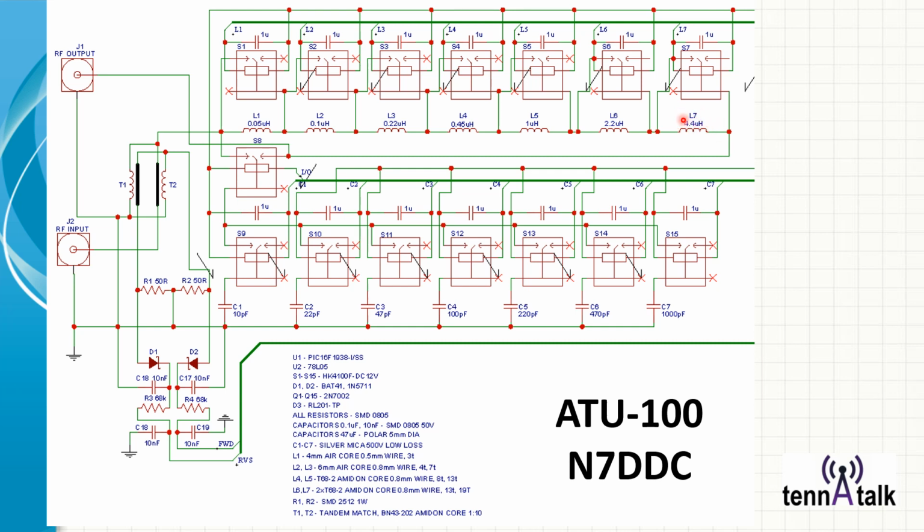Well, guess what? These are relays, and they're used to short out selectively the inductors we don't want in the path. So what'll happen is if we've got, let's say, the first 2 shorted out, the current goes through the relay instead of through the inductor. And then this one, the relay is open, it's not shorted. So we're adding 0.22 microhenries. And so you can see that by shorting or not shorting the inductors, we can make any configuration out of these 7 inductors that you have, and it's typically 7.